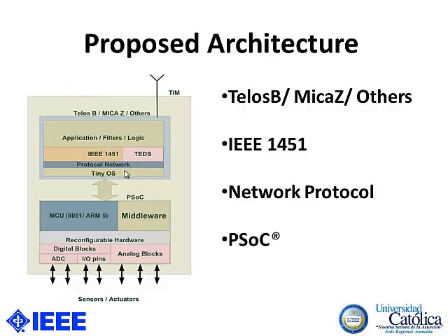In the project that I'm going to present, we use a TelosB platform modification. This TelosB platform runs TinyOS, the Tiny Operating System. So you can put whatever network protocol you want, because in wireless sensor networks, everyone tries to do their best network protocol. You can prove different kinds of protocols, but because it's based on the IEEE 1451 standard, you can connect between them.